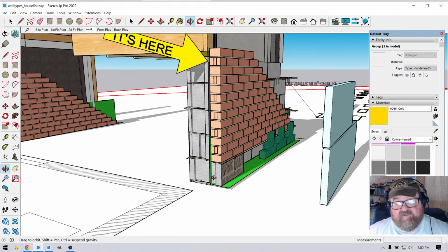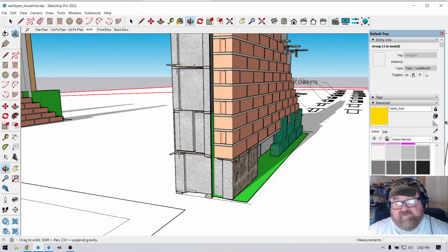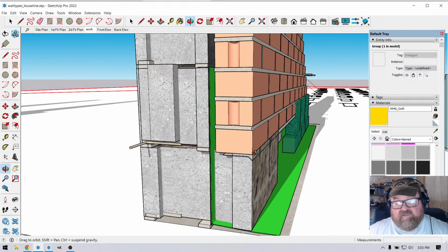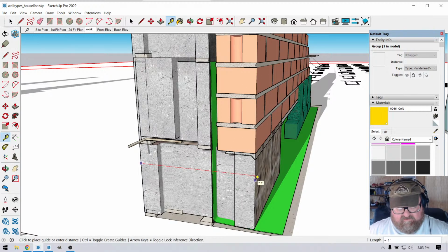Because what you'll do is lay these wider blocks below grade, right? So you would lay these up to maybe here, if the grade was going to come up that far, but that saves you on brick, right? So that gives you a brick ledge, and people will argue about this air gap all day long. But all they have to do is go out to a construction site, and they're actually 11 and 5/8. Okay.